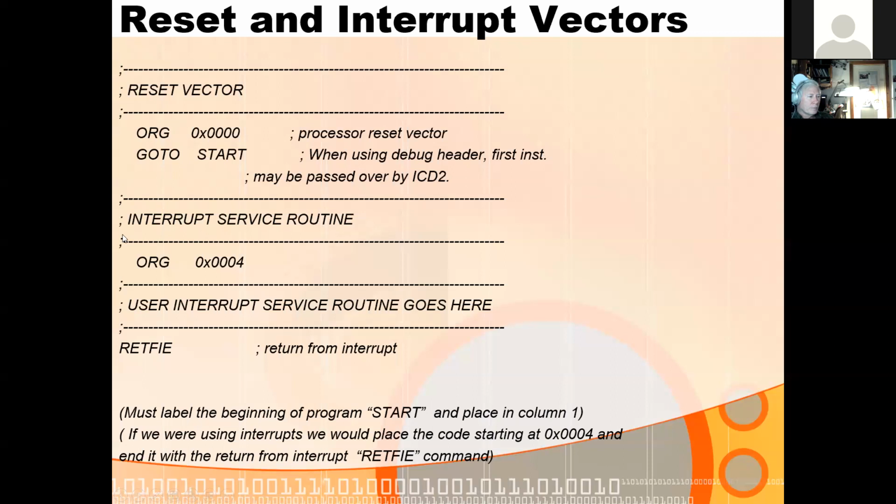Okay, so that 4th register is hard coded for interrupt service. So this isn't a register. This is a location in program memory. So remember that it's always an interrupt then. Yes. Every time you interrupt, the processor always jumps to location 4.